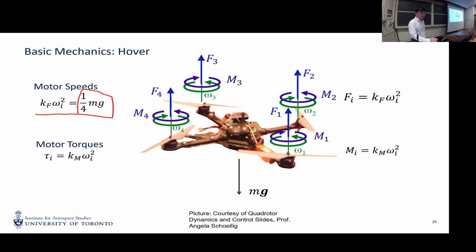The thrust on each rotor is a quarter of the total gravity. And then by using this formula, and the Kf is a function of the Ct, which you just get from the UIUC database, in the end you can figure out the omega. So you can backtrack and get an estimation of the omega.